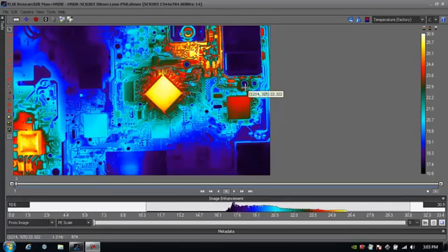The entire board should be about the same temperature, just resting at ambient. However, due to emissivity and reflections, there are apparent temperature differences across the board. One way to help remove those apparent temperature differences and see just the delta temperature rise is with image subtraction.